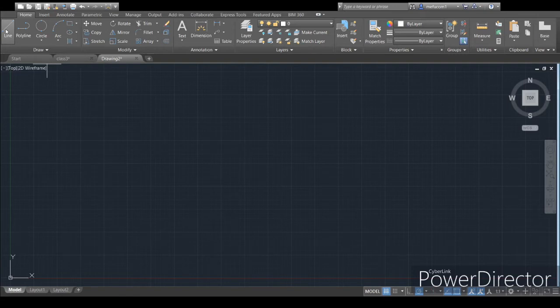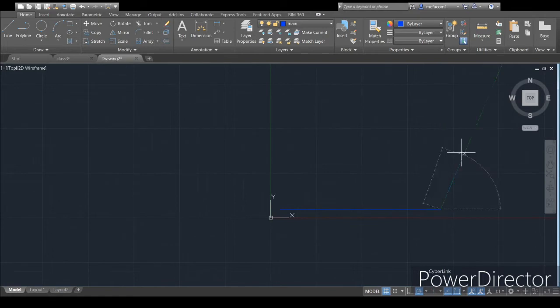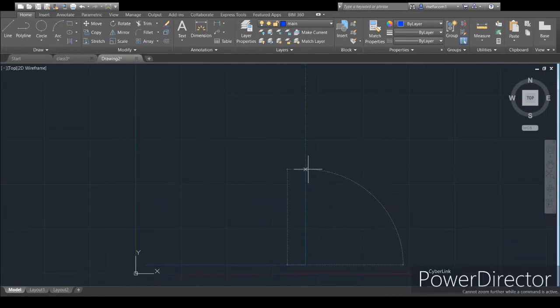Now what we're doing is the views. It's front view, side view, and top view. I'm going to start off by making that. So I'm going to choose which layer I'm using. That's going to be my main color. And it's going to be from the front view, 44 wide. So 44, enter. I'm going to shrink this down. The height's going to be at 64.